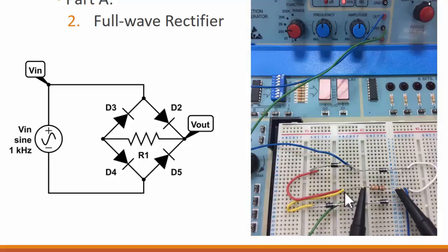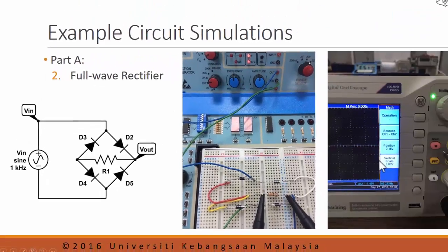When you do this, effectively what you're doing is an operation whereby we want to know the voltage across the resistor. So we measure the voltage at one point of the resistor and then subtract the voltage at the other end of the resistor. So effectively, we know exactly what the voltage across the resistor is. So that is what we want to measure. So to do that, one probe goes to one side of the resistor and the other one goes to the other.